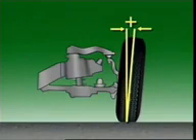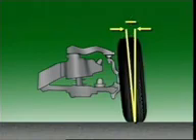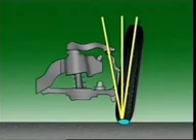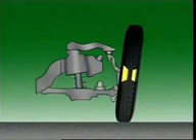This section examines camber. Camber is viewed from the front of the vehicle, and it is the angle of tilt of the wheel from the vertical. A wheel that leans away from the vertical at the top is said to have positive camber. A wheel that leans towards the vehicle is said to have negative camber. On earlier vehicles with narrow tires with a large diameter, large camber angles were used to bring the center line of tire road contact closer to the steering axis. It also ensured the vehicle weight was carried by the large inner bearing.